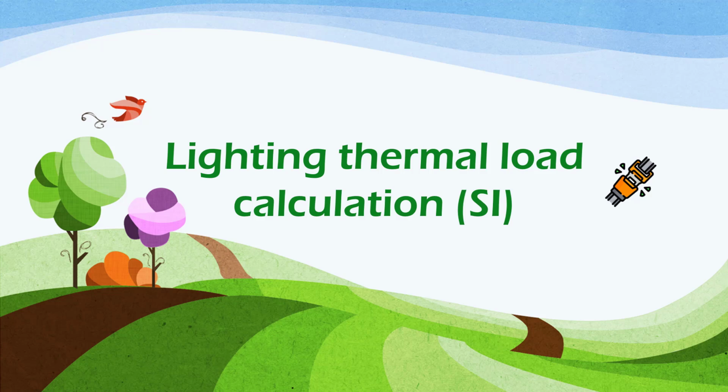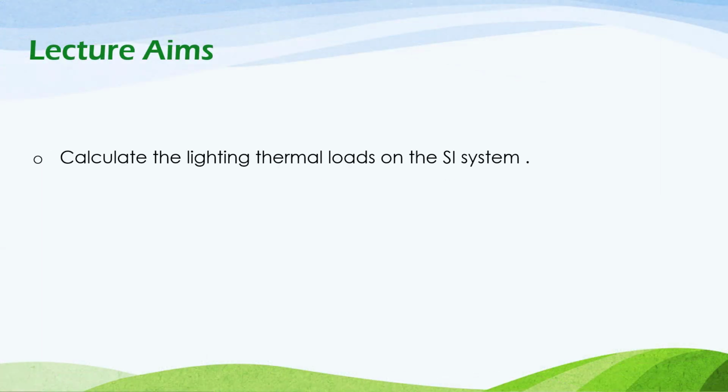In this tutorial, we will start illustrating the interior thermal load calculations according to the SI system standards, and we will start with the lighting thermal load calculations. So fasten your belt and let's get started. The aim of this tutorial is to know how to calculate the thermal load for the lighting system inside the building, as the lighting loads are interior elements inside the building spaces, so it's considered to be one of the interior loads as we learned before.